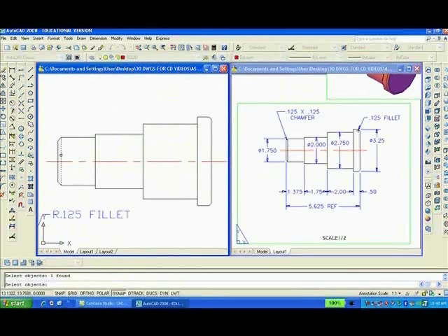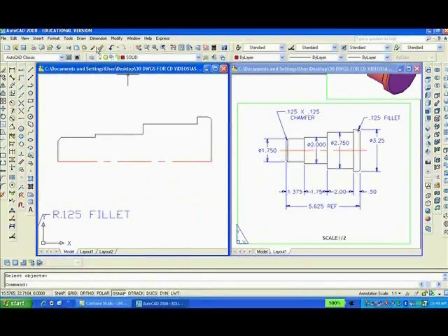So what I'll do is to erase this. Well, there's a lot of ways of doing it. I suppose the fastest way would be to use the fillet command. F enter. Oh, wrong fillet. Undo. F enter, R enter, 0. Remember, fillet radius 0. Now that I got fillet radius 0, I can clean up this intersection and this one, as well as this one. And I can also fillet this, fillet that, and erase. And use the match properties to make that a solid line.